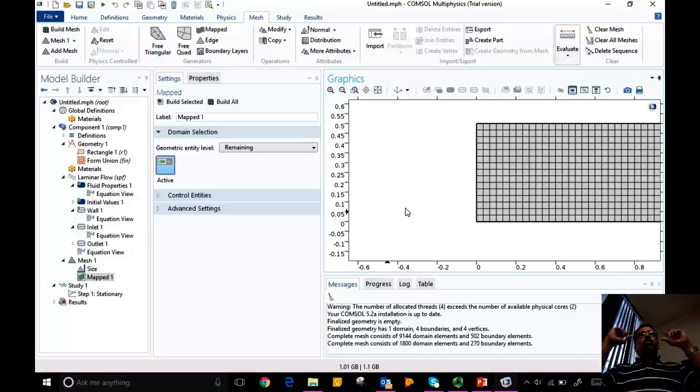But using a coarse mesh where you have a fine boundary layer is going to lead you to an incorrect answer. So they are erring on the safe side, saying, if you tell me that it's Navier-Stokes and a wall, before I know the viscosity, I'm going to put fine grids there, right? The third piece of information that you need is what is the viscosity, to decide to what extent I should put fine grids near the wall.